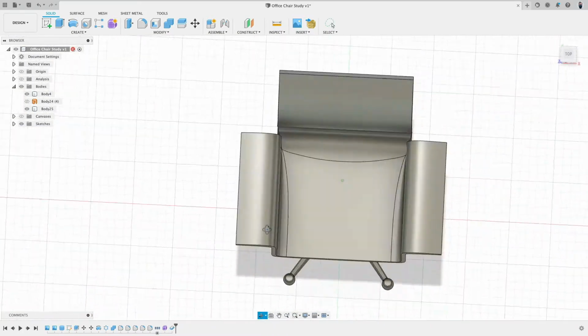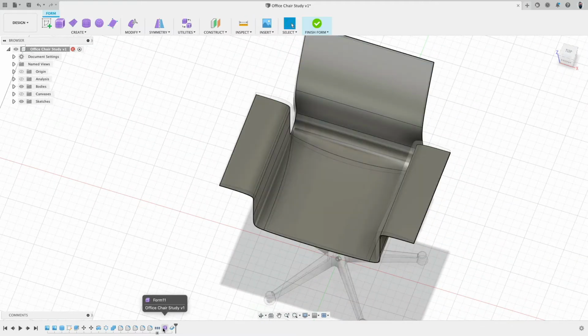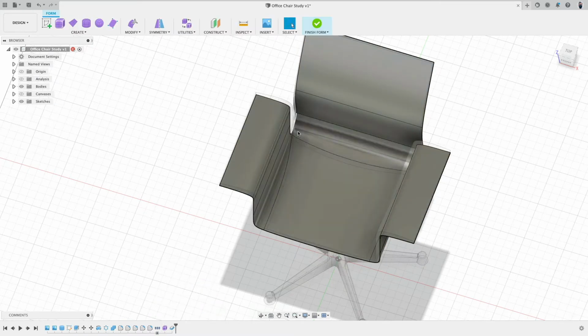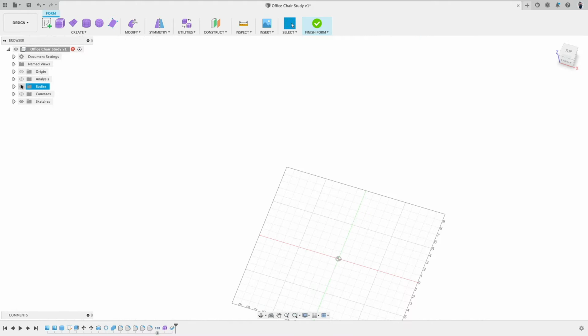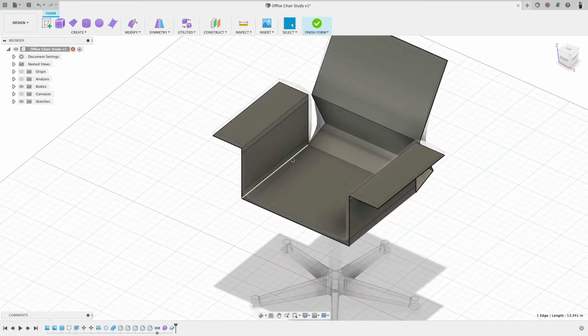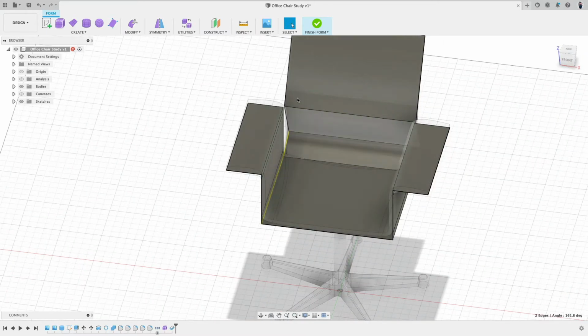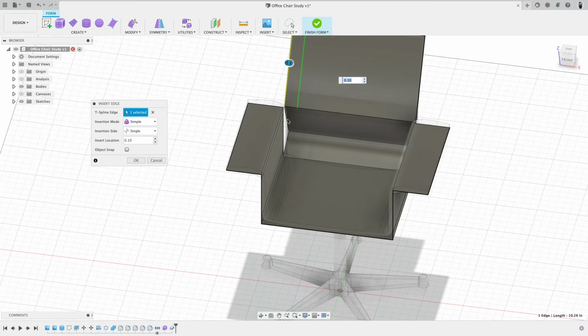For what we're doing, maybe this is fine, but I have a hunch how we can quickly fix this. Let's double click onto the form or right click and say edit and go back to this box view. And then you will see that here we have the line and line. I would like actually to do the following. I need to have another groove here. So to do this, it's quite easy. Insert edge here, here, here, 0.5. So at the center.